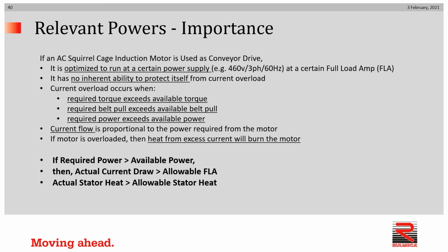Note that current flow in the stator is proportional to the power required from the motor. If the motor is overloaded, then heat from excess current, as you've seen, will cause the stator to burn. If required power exceeds available power, failure. Actual current draw will exceed allowable FLA, failure. Actual stator heat will be beyond the ability of the stator to sustain that heat, failure.